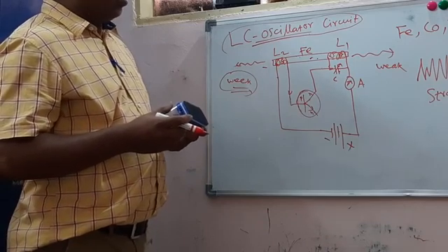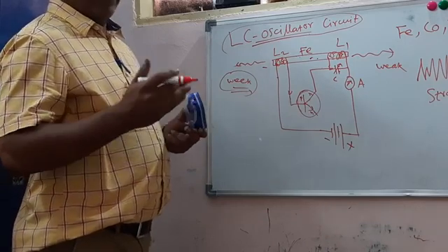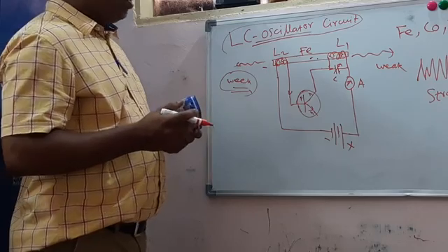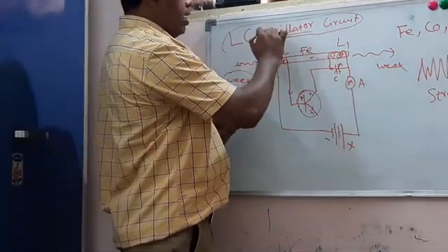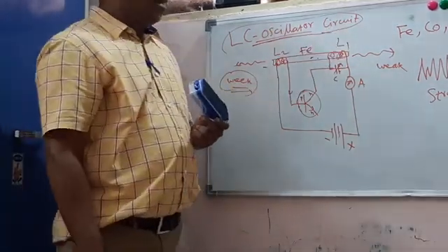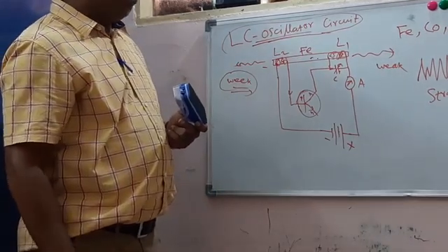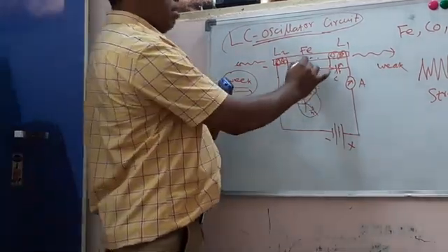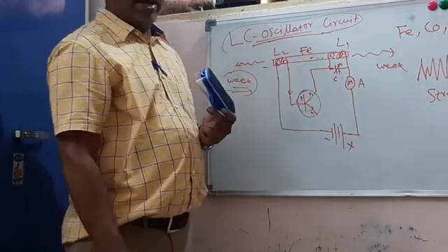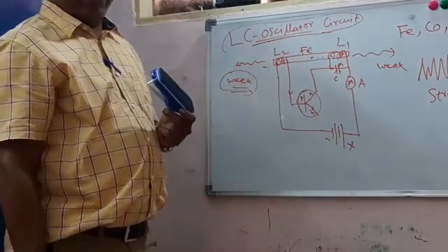Okay, so it will vary for different materials. So one should match the frequency of the LC oscillator with the frequency of the material's intrinsic magnetostriction frequency.